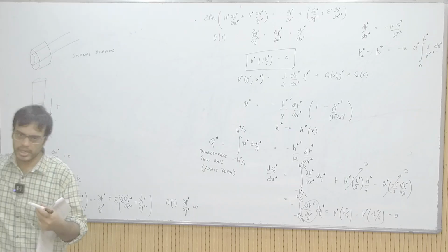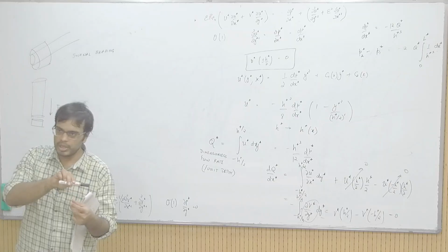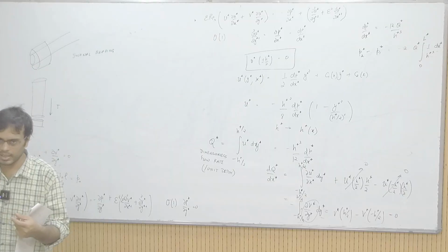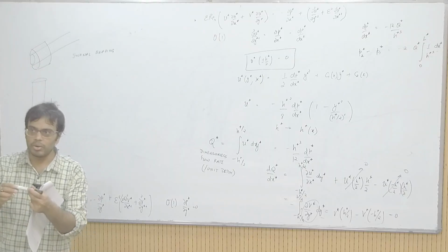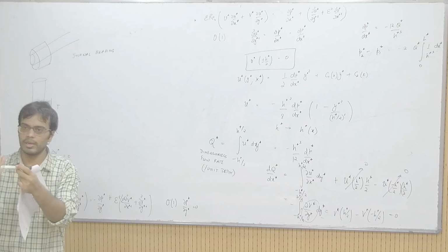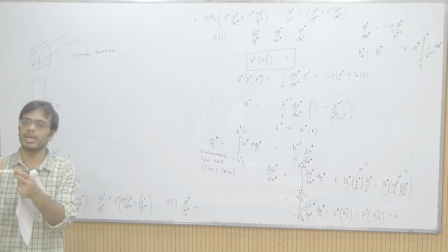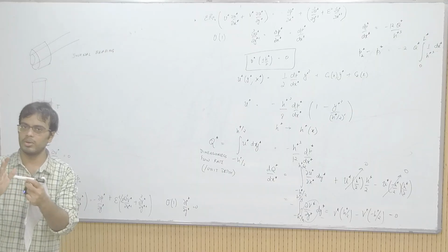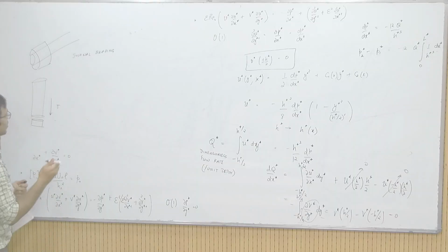If it is pushing air outside, and the plane is moving like this, then the shaft will be experiencing a thrust like this, right. So, how do you make sure that it maintains a smooth contact, is able to rotate and also sustain this thrust. These are called thrust bearings.